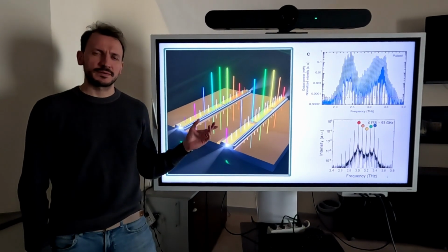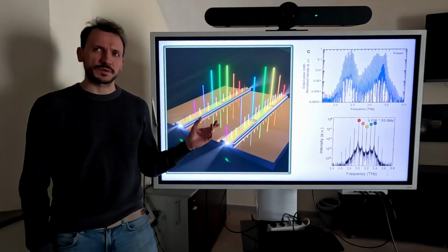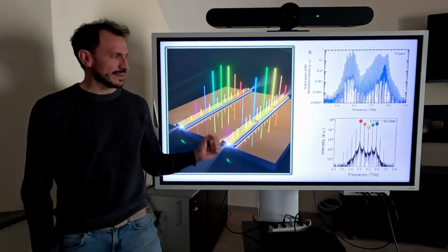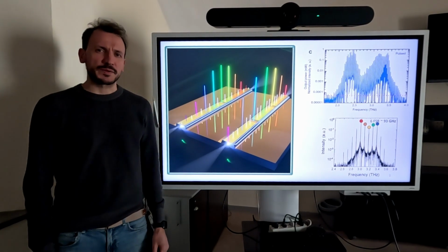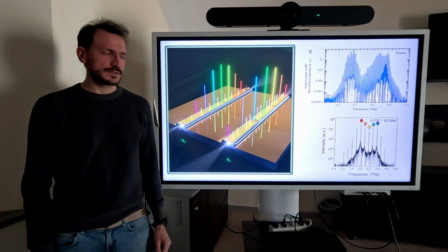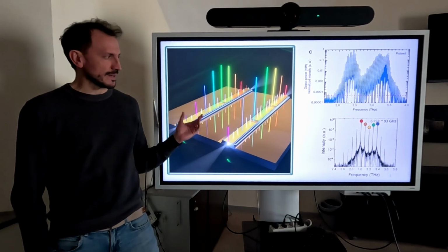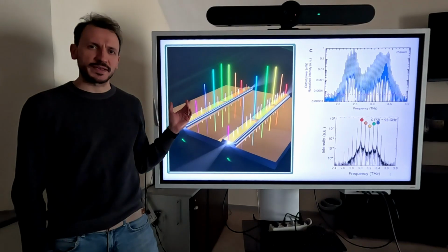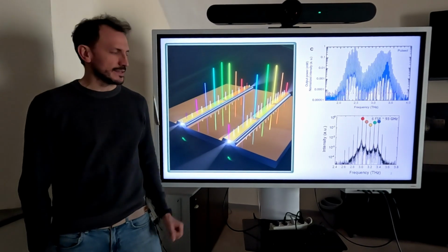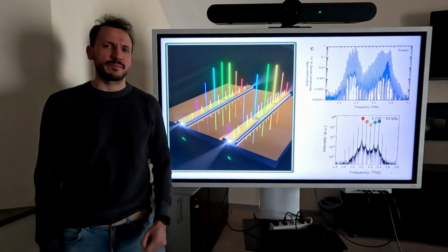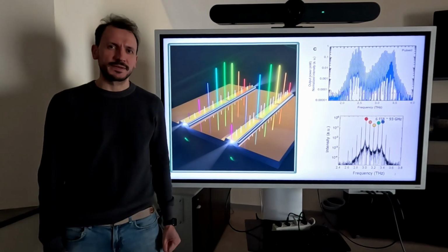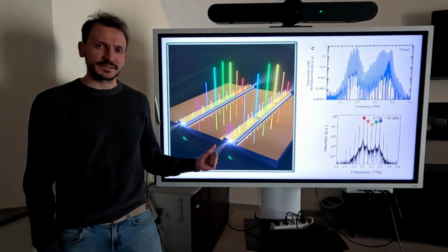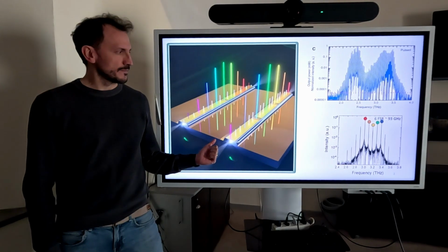Concept on the realization of harmonic frequency combs in the project T-Next. Optical frequency combs are light sources whose emission spectrum is characterized by evenly spaced optical modes. In the terahertz range, this can be realized by quantum cascade lasers, which are semiconductor-based terahertz sources.